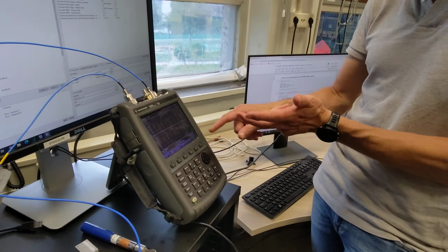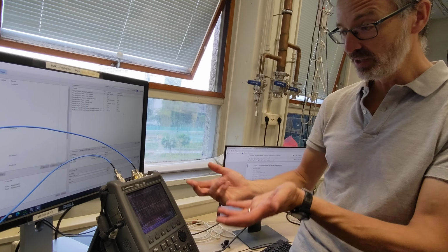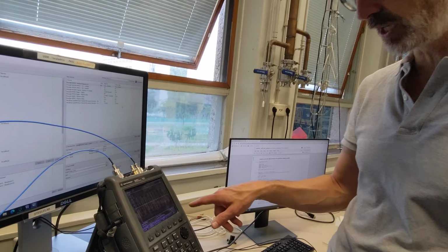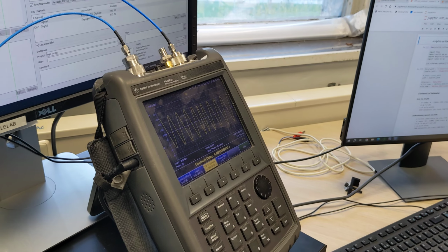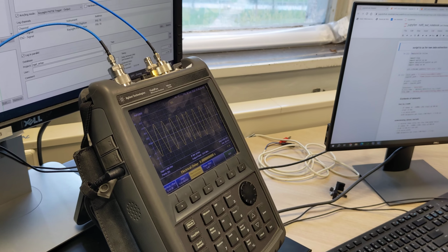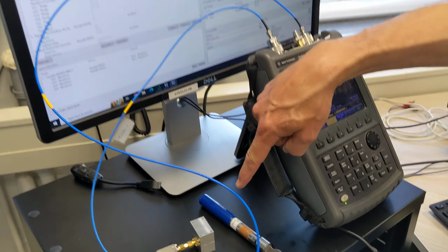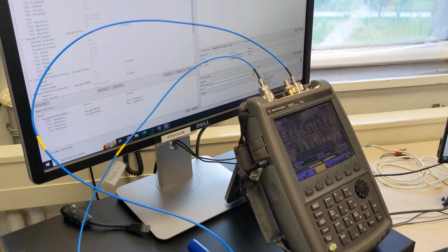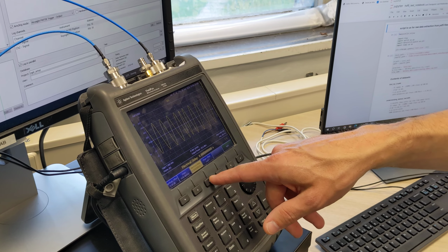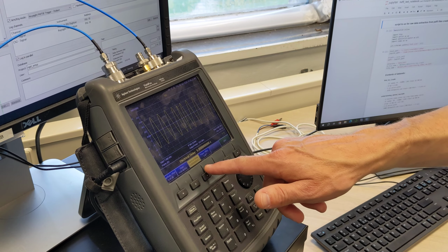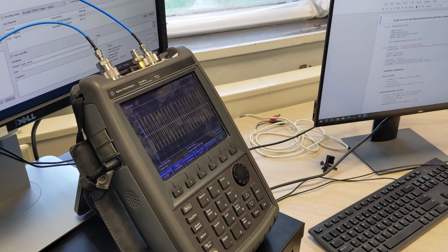That's so the real part looks like the real part of a formula in MATLAB or in Python, and the imaginary part looks like it should. Well, okay, but let's first get rid of this electrical delay. The way this works, it's about 1 nanosecond per foot in a cable. I work in feet from the olden days. 3 feet is a meter. So let's assume this may be a meter, so it's maybe 30 nanoseconds. So then we can go here, 30 nanoseconds.